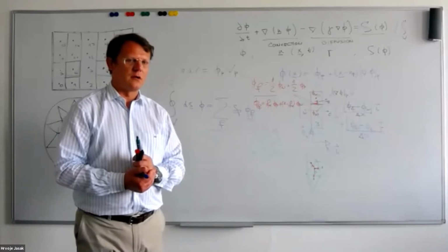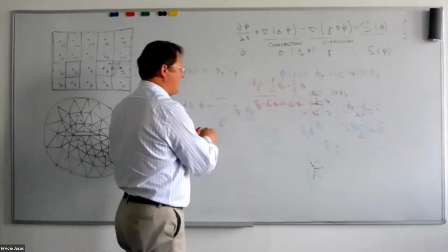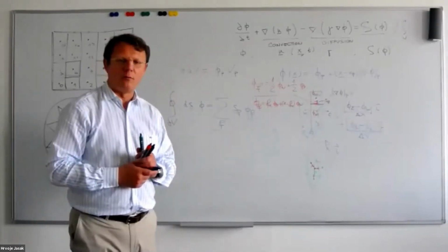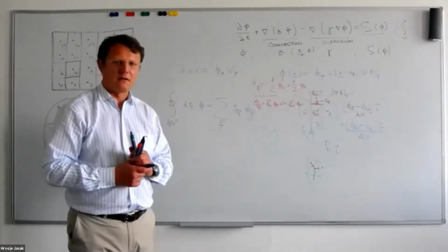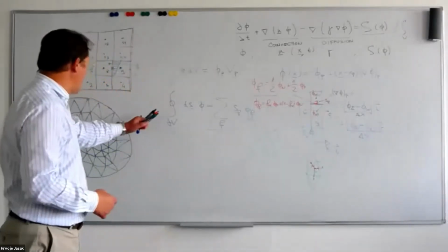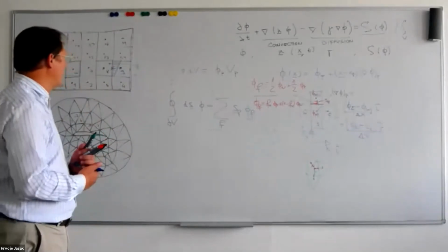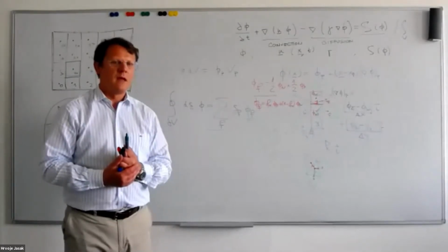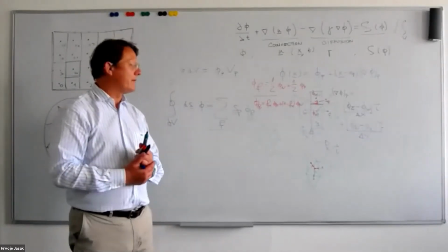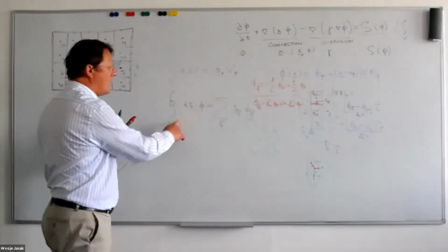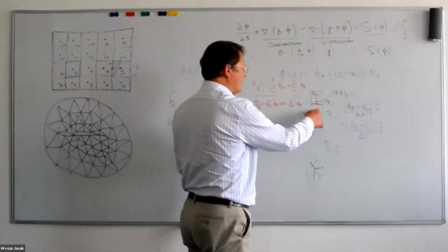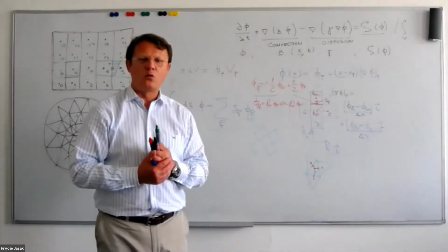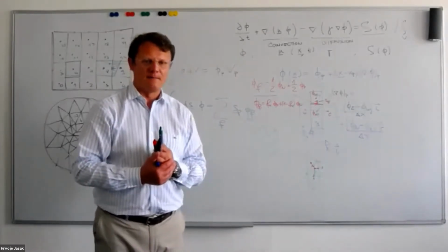Two important messages here. By using Gauss's theorem, which is in fact a generalized form of my right minus left, top minus bottom finite difference gradient, I can evaluate the gradient on any type of mesh, including triangular, polyhedral, hexahedral, or indeed any other valid mesh. And secondly, in order to assemble the discretization of the surface integral, the cells that appear in the solution vector in connection with my cell P will be the ones with which P shares a face.